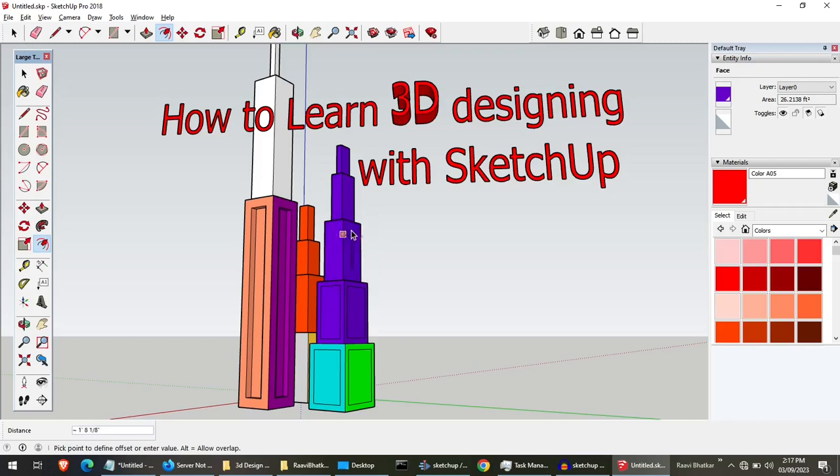If you have any trouble, you can just move it slightly right or left and see where the offset is coming, and then click it again. Once again click on the edge and then make some offsets like this. Now let's take the push pull tool and make them like this.